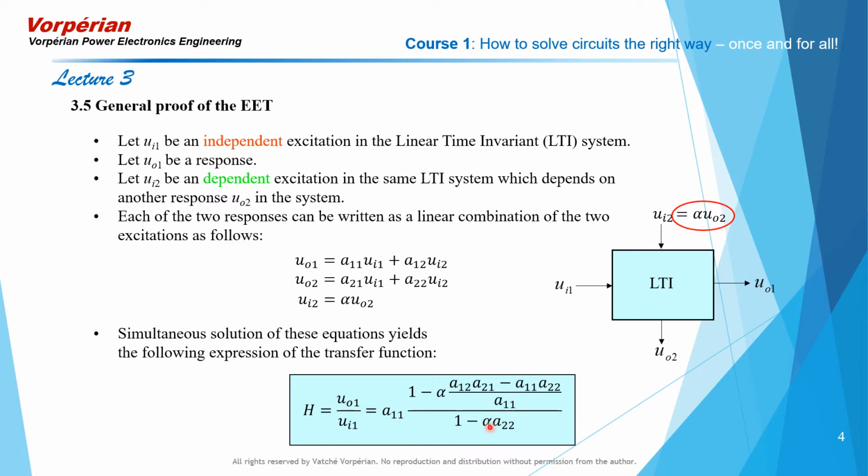You are never going to have to write these three equations, solve them like this, and perform the algebra of A11, A22, A12, A21, and this whole business that you see in front of you. This is not the formula that you are going to use to apply the extra element theorem. What we're going to do is interpret these coefficients properly inside the circuit diagram and have an operational way of determining them. And that will become the extra element theorem or its application, proper application to circuit analysis.